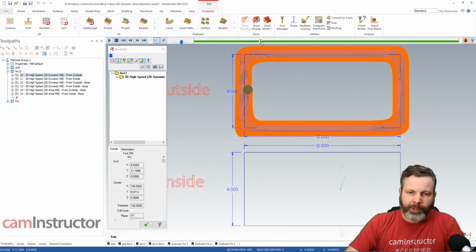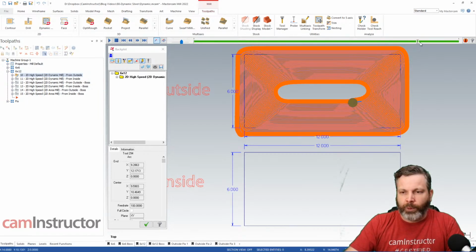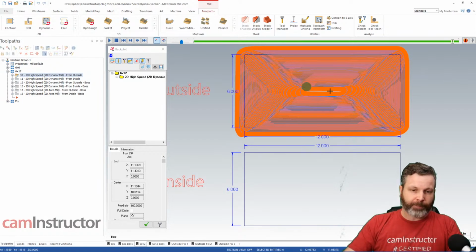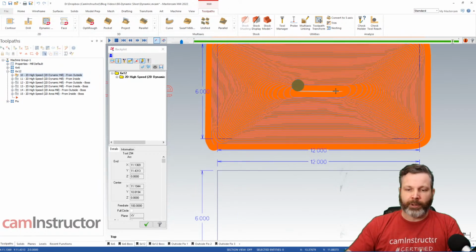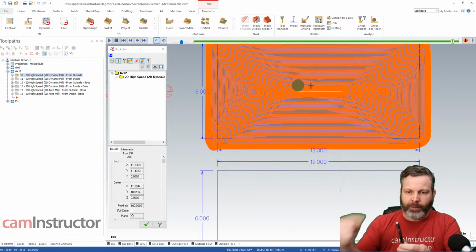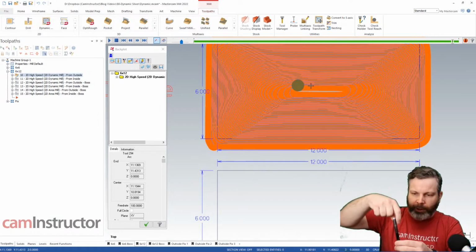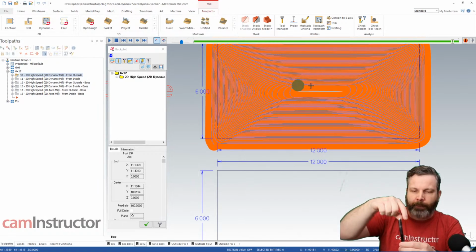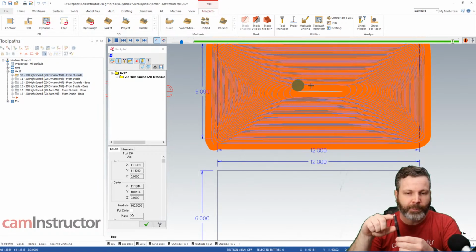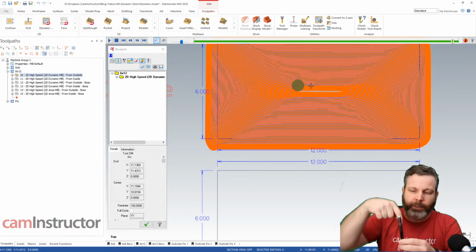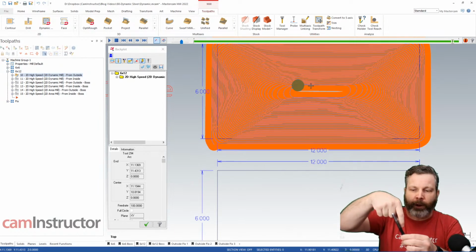The problem with this shape of part comes when we get close to the middle. Right in here, you're seeing this little sliver that's left behind. So what can happen here? Let's say this pen is the material. That's that sliver of material right in the middle, and this is my cutter. When I come down this side of the material, especially if you're doing a very deep cut, the cutting force applied to this material, if it's got some ductility to it, can deflect away from the tool.